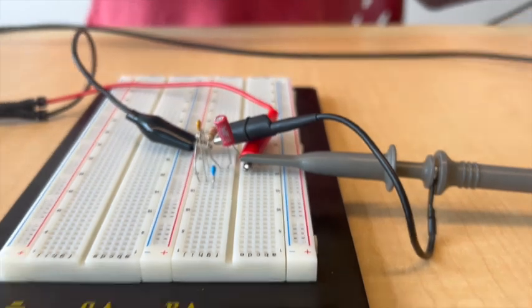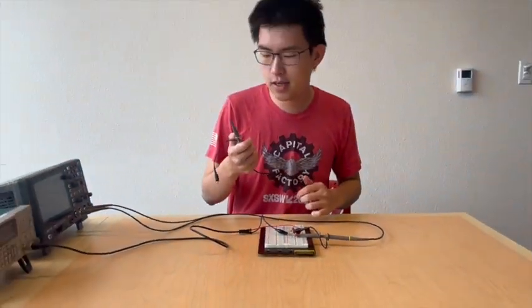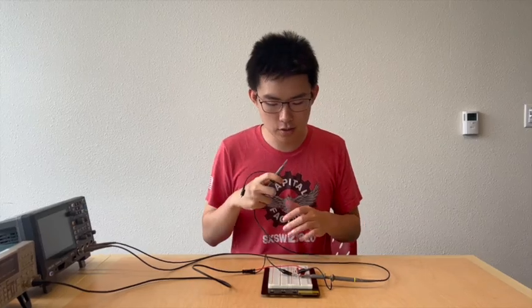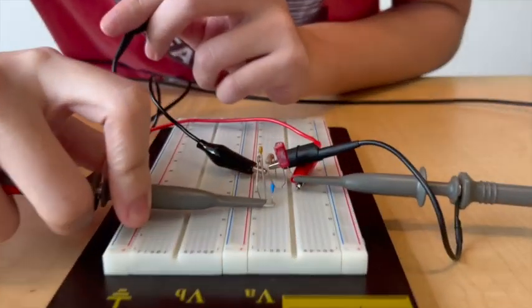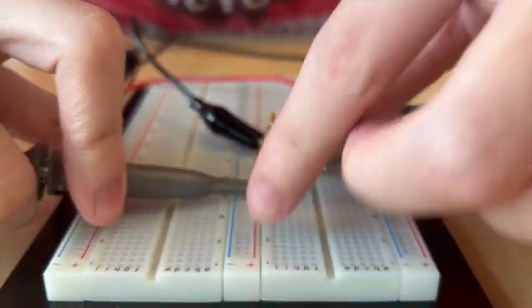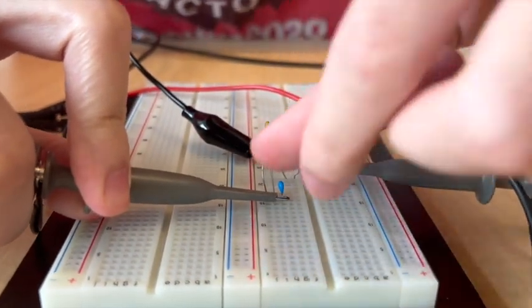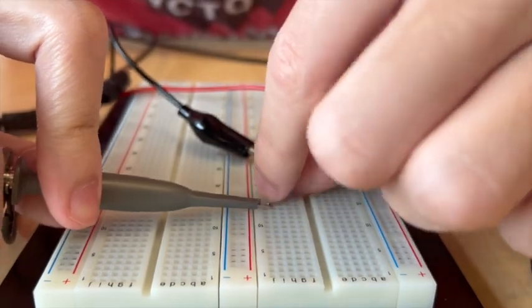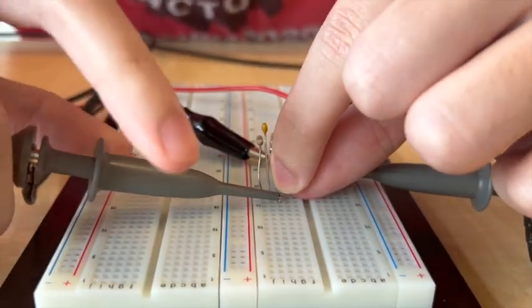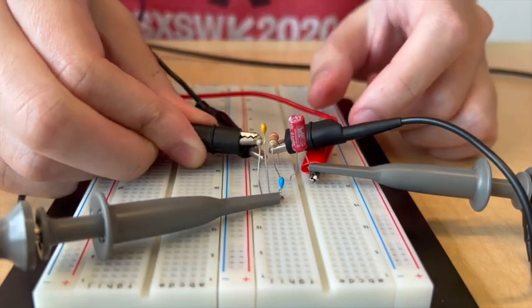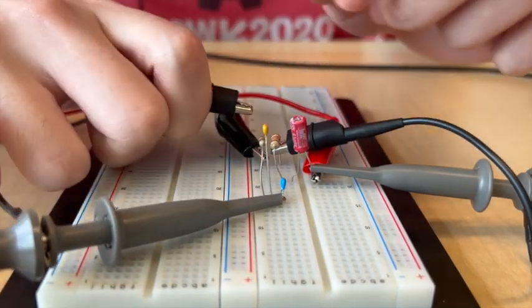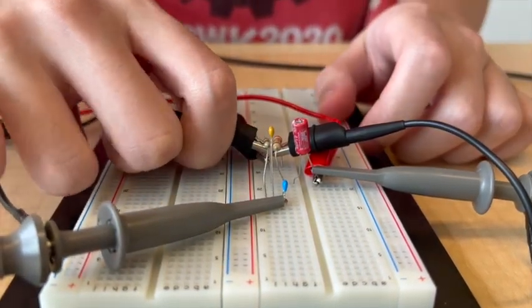All right, there we go. Now we are going to take our second oscilloscope lead, which is our output lead, and we are going to hook it up to our circuit with our ground in the same location and a positive on our 150 pico capacitor, which is, in this case, really small. There we go. And then we want to hook it up to the ground. There we go.